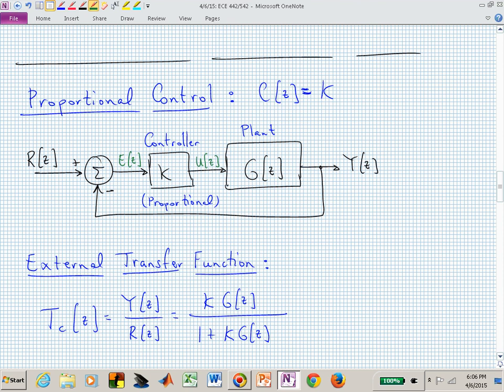So you might think, oh, look at this system, it's beautiful between R and Y. You plug it in or you energize it, and after a little while it's burned up and not working anymore, or it's been chattering and you've broken something because an internal signal has gone unbounded, because you tried to cancel an unstable pole or zero with your controller. Does that answer your question?